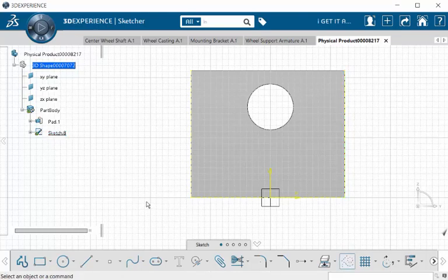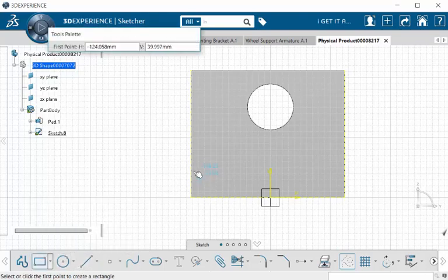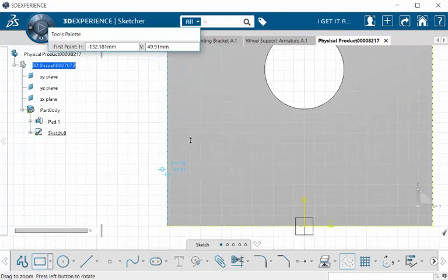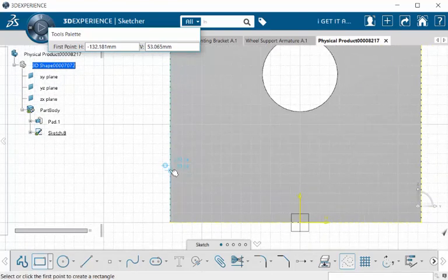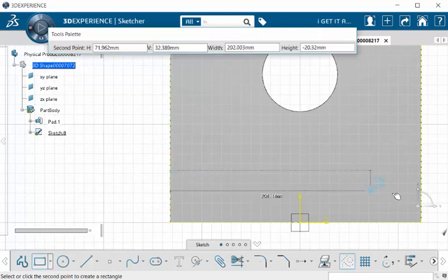Now, what this allows me to do is when I select any of these circles, lines, or rectangle features and tools, it allows me to select on those construction elements. And notice here, I'm going to select into that point and make sure that that little blue concentric dot is filled.